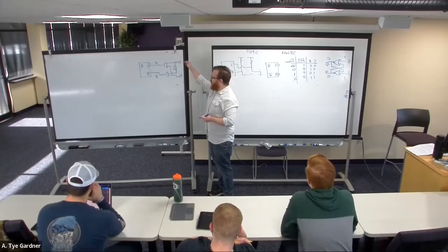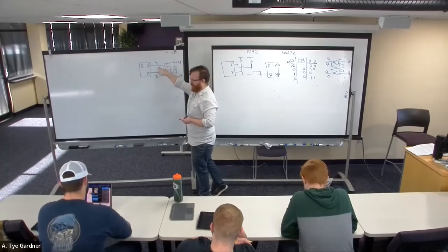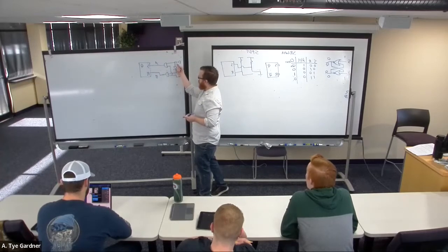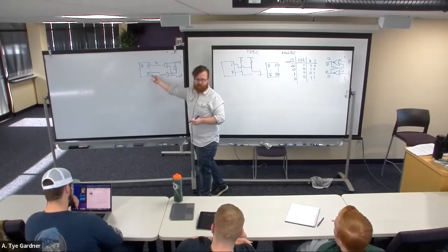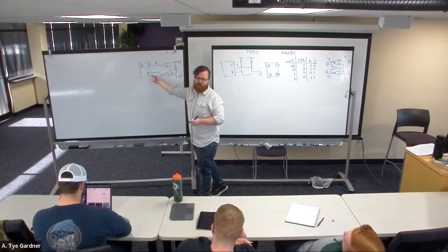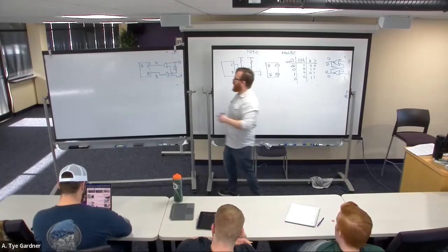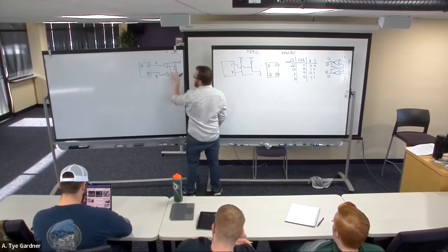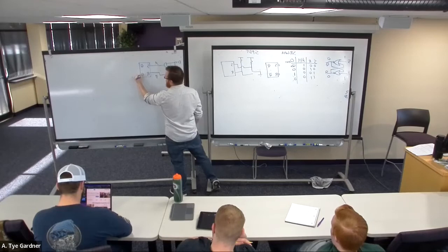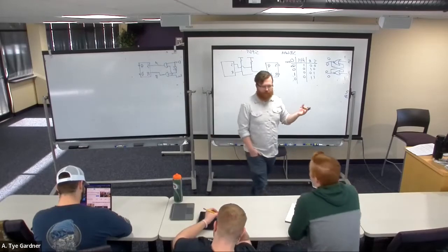Now, if D is 0, that puts a 0 here, 0 here. So let's assume that enable is 1, 0, we're not setting, but if D is 0, then there's a 1 that comes through here, passes, and resets. Okay. So now we're inverting, unfortunately, at this point, right? Because if I have a 0 here, I get a 0 here, I'm not setting. So well, it's okay. I can then just call my output Q and Q bar active low, and everything's fine.